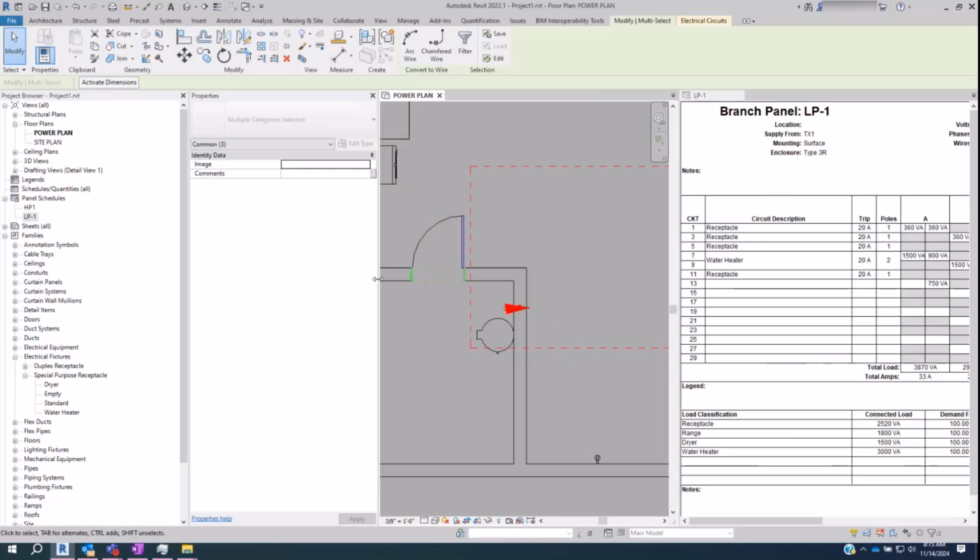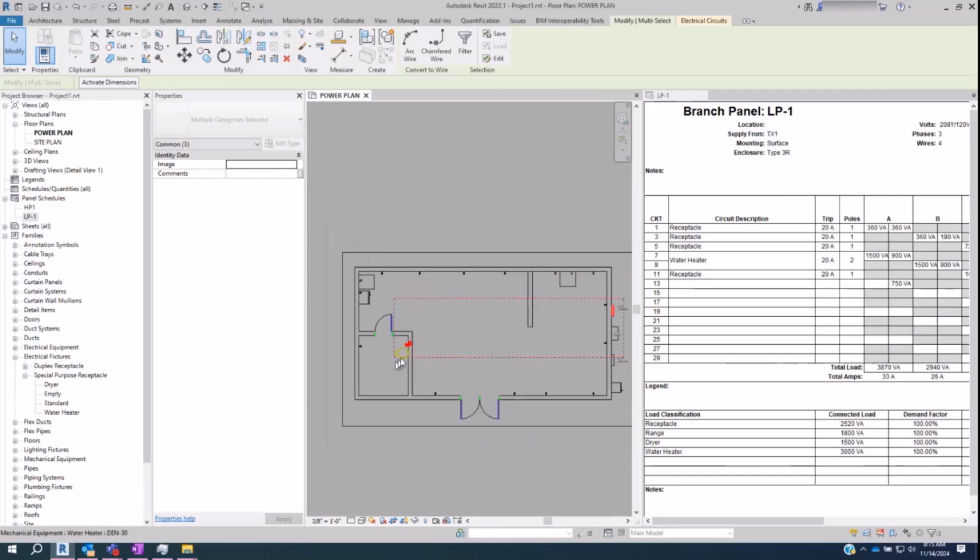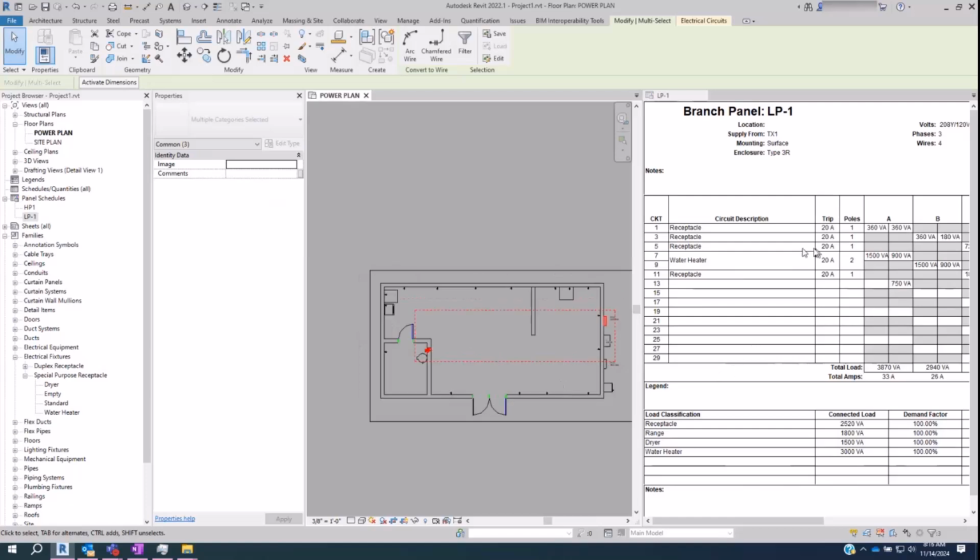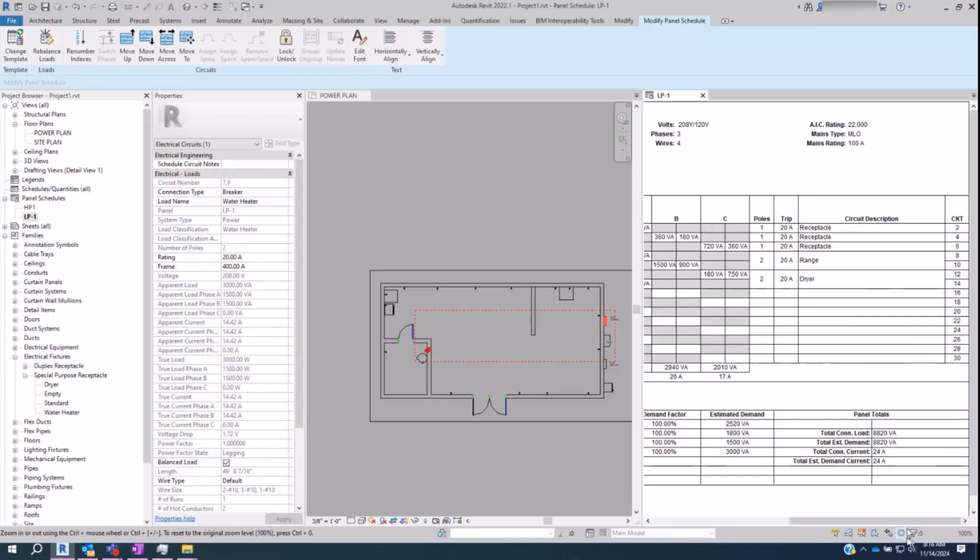It is. I understand your question. And so a lot of the time it's good to get all the stuff circuited and then go back and trim your panel down. So for instance, I could have put 42 circuits in here instead of 30. I could have put 60. I could have put 86. Those are common sized panels. And then when everything was all said and done, and yes, this is all the equipment I'm putting in here, great. If I've got 50 spaces, well, I don't need 50 spaces. So I'm going to trim that down to the next most common circuit quantity out there.